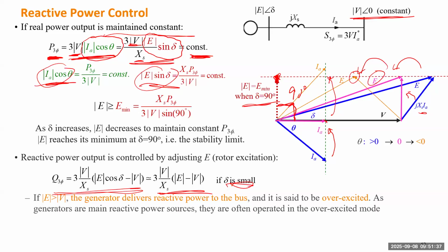So in a practical power system, most of the loads actually have internal reactance. As long as they have some inductance, they behave as reactance and consume some reactive power. The overall complex power consumed by the transmission line also has positive reactive power, so the transmission line is also a reactive load. So finally, the only reactive sources in the power system will be generators and some capacitors.